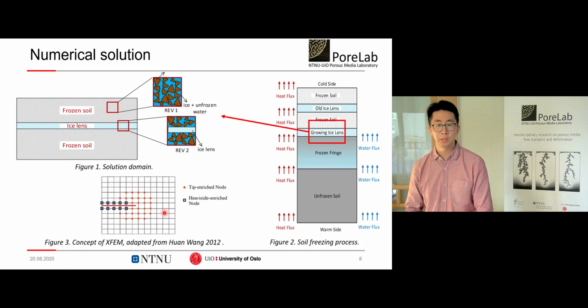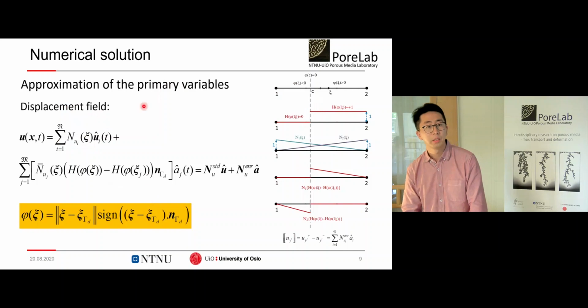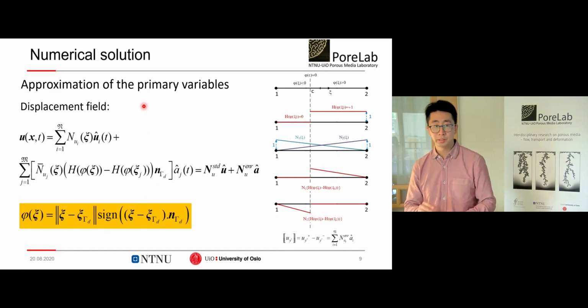Here we introduce the extended finite element method, XFEM, and the key advantage of XFEM is that we don't need to update the finite element mesh to track the crack path. It extends the classical finite element method by enriching the solution domain of the differential equations with a discontinuous function. And there are three primary variables in our equations: displacement, temperature, and pressure.